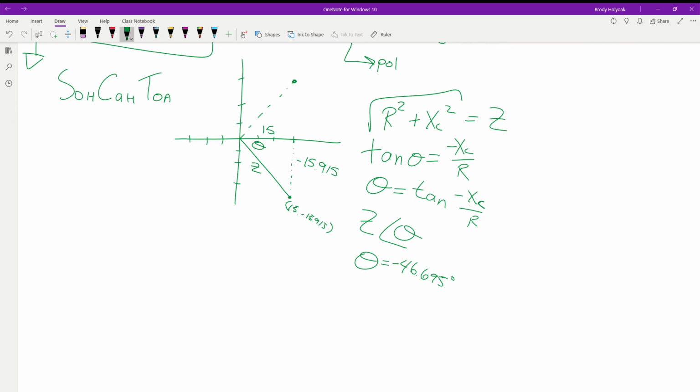If these are close, we should start seeing it approach 45 degrees. And we'll know if it's getting smaller or larger than 45 degrees based on which is bigger. The capacitive reactance is bigger, so it's heading towards the negative 90. So our impedance total is, what did we get for this value up here for our Z? 21.87. Solving for theta was using tangent. This one was just using Pythagorean's theorem.